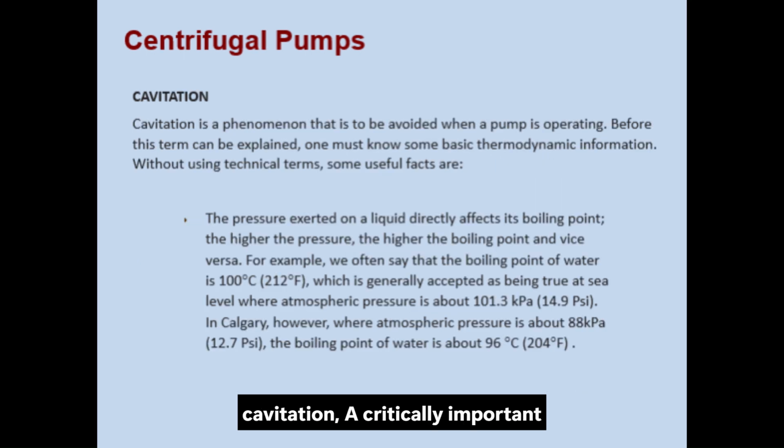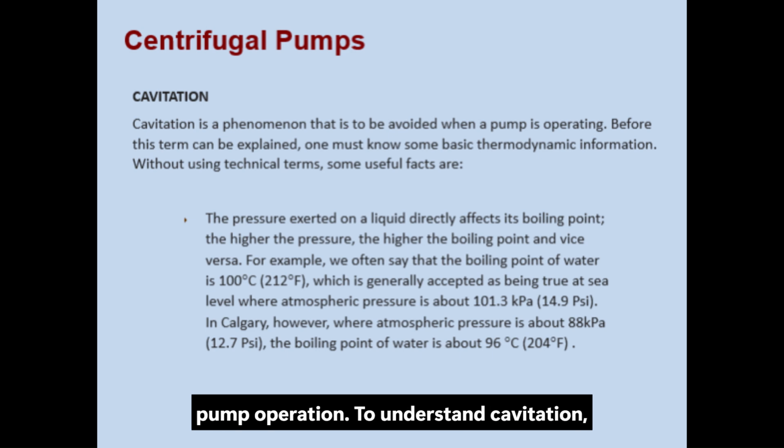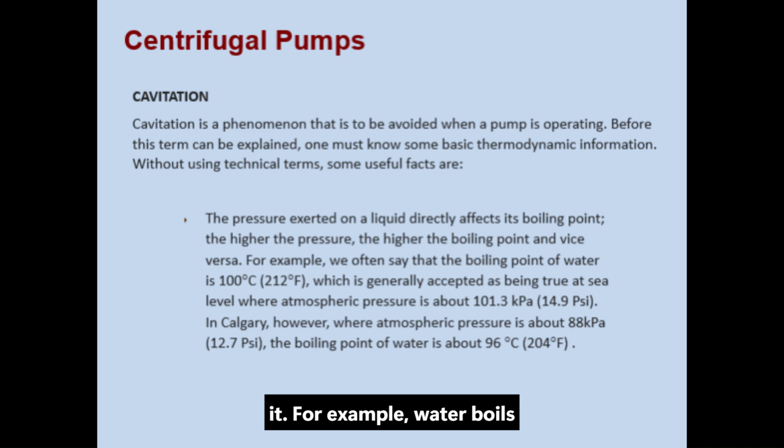We now address cavitation, a critically important phenomenon that must be avoided during pump operation. To understand cavitation, we first need some basic thermodynamic knowledge. The pressure exerted on a liquid directly affects its boiling point. Higher pressure raises the boiling point, while lower pressure decreases it. For example, water boils at 100 degrees Celsius at sea level where atmospheric pressure is about 101.3 kilopascals. In Calgary, where atmospheric pressure is roughly 88 kilopascals, the boiling point drops to approximately 96 degrees Celsius.